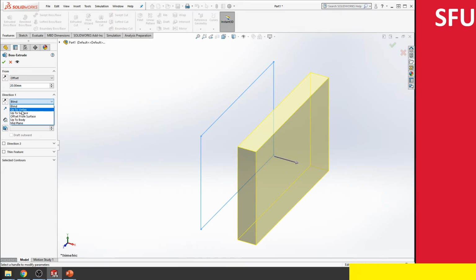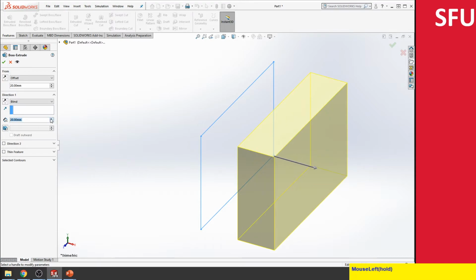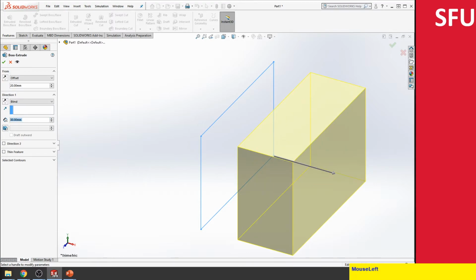Instead of blind, you can drop down and select up to vertex, up to surface, offset from a surface, up to a body, mid plane, and all of these options. These tell you how the extrusion is actually created. For now, since we don't have any other surfaces or vertices, we are going to click blind and just give it a distance. So maybe let's make this 20 or 30 millimeters.